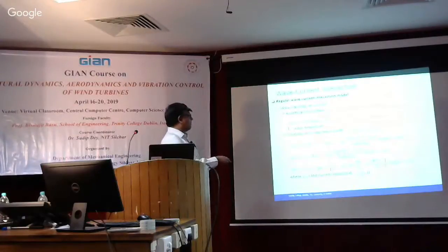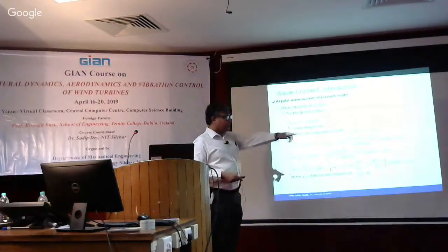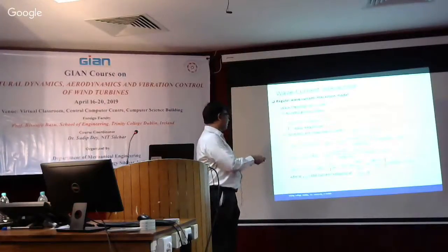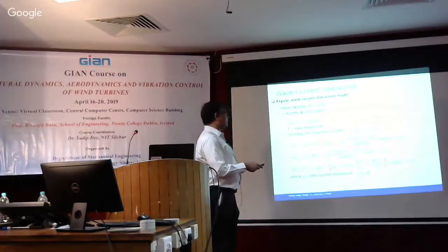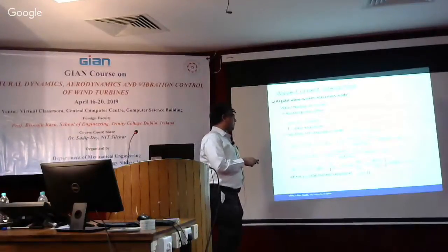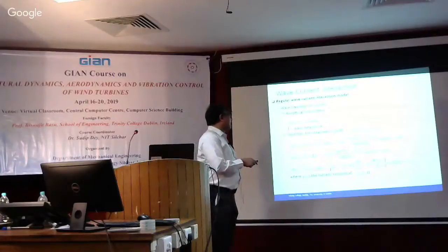And then the solutions are obtained as this is your sort of potential flow equivalent here, and then U, W, and P are given by these three expressions here. And note again here, considering everything as sine and cosine terms, and obviously the depth variation is given by this hyperbolic function in terms of z, and the amplitude here has actually a shift now from frequency omega with a value of u0 times k, where u0 is the velocity and k is the wave number.